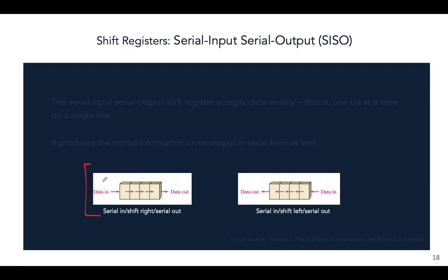This is a register, a very basic description. These are the four flip-flops we're talking about. For illustration purposes, we have used a 4-bit register, so we have four flip-flops. The data goes in from one end, it comes out from the other end. The same thing is happening here, except the direction of the flow is different. That is the only difference between these two.